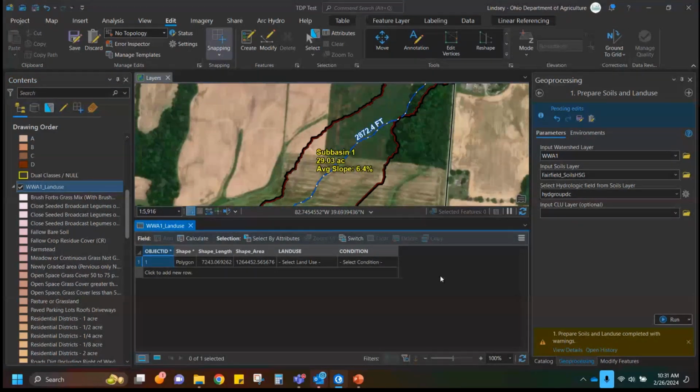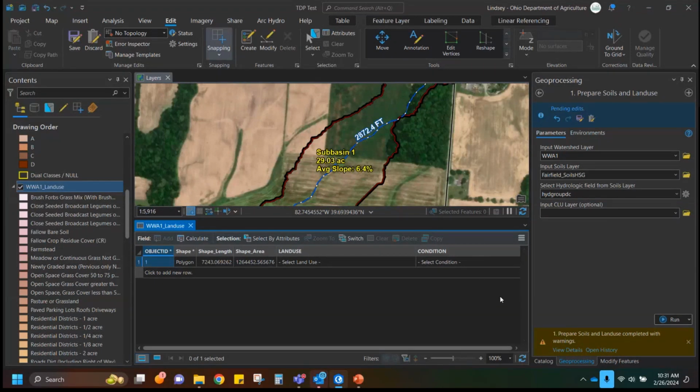Now, something about ArcPro that is different than ArcMap: anytime you're editing in ArcPro, if you've made no changes to your settings, your editor is automatically on. So you do not have to turn it on to change this stuff. That was not the case in ArcMap. So take that into consideration. Makes this actually a little bit easier.